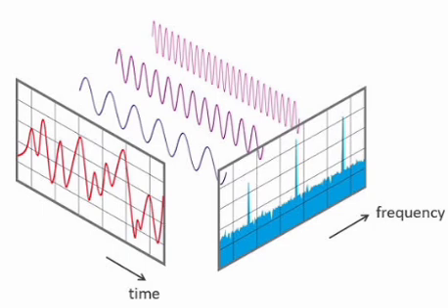Any band-limited signal x of t is uniquely determined by its samples if the sampling frequency omega s is greater than twice the maximum frequency omega m present in the signal. This is the sampling theorem: omega s greater than 2 omega m. There are two types of sampling: ideal, instantaneous sampling with zero pulse width, and practical sampling with non-zero pulse width. The first one is natural sampling, the second is flat top sampling.